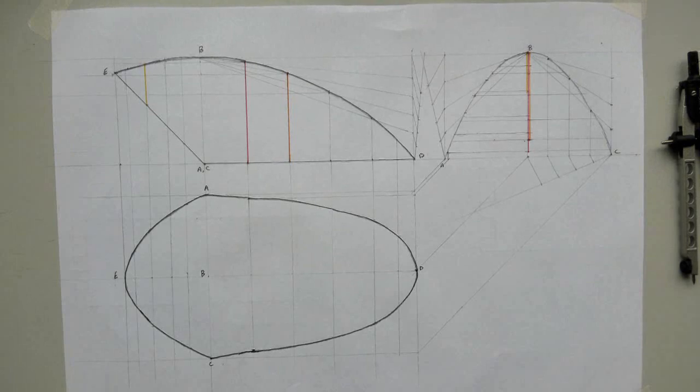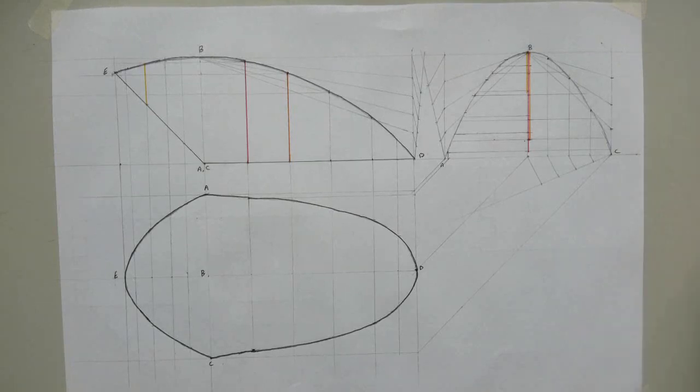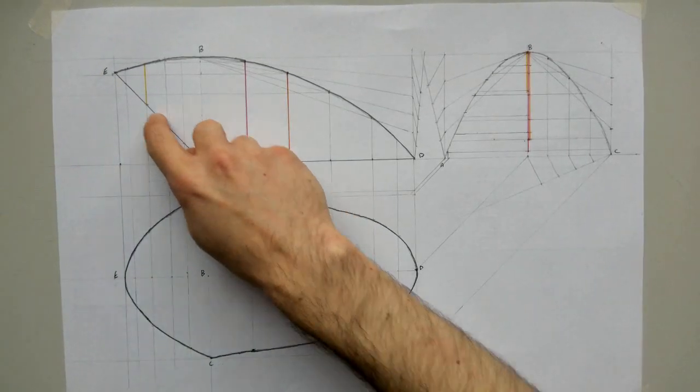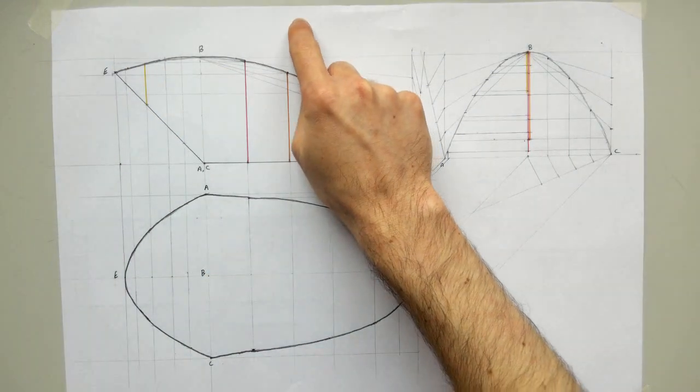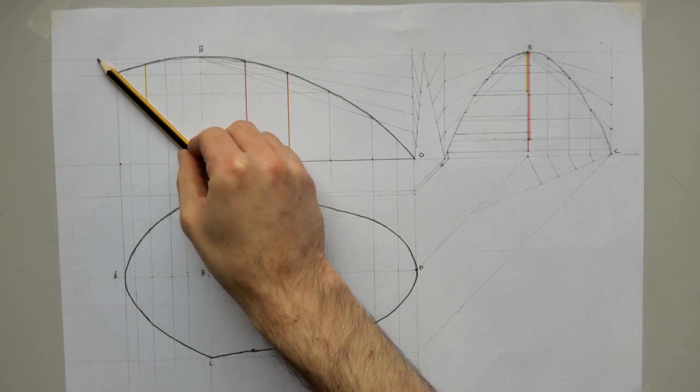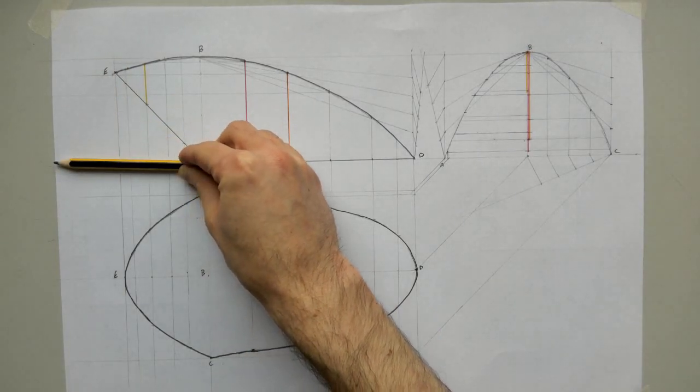So for this part of the question, I'm going to use rebatment to actually draw the true shape instead of drawing an auxiliary view. An auxiliary view, if anybody wants to do, just take their view in looking this way, where they have their true length here, or looking in this way. I have not much room in my sheet to actually do an auxiliary view going either way. So what I'm going to do is use rebatment, where I actually flatten the surface down on the ground to see it as a true shape and plan.